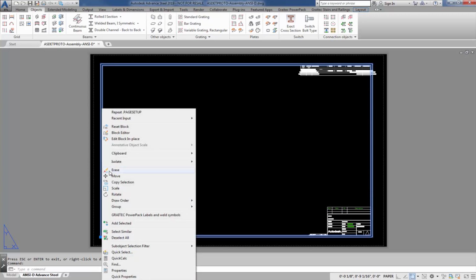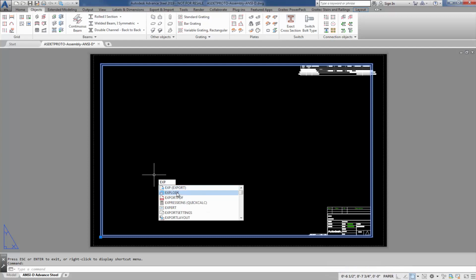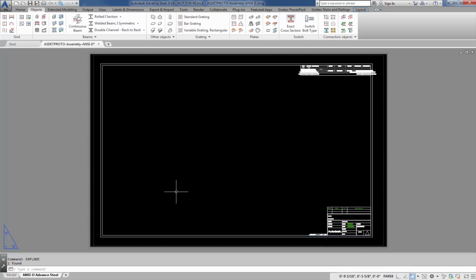So what I should do is explode it. Let's not erase, we want to explode. So let me just type explode, and after we explode it, we'll do some modifications.